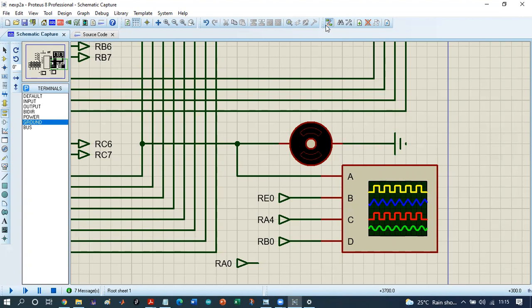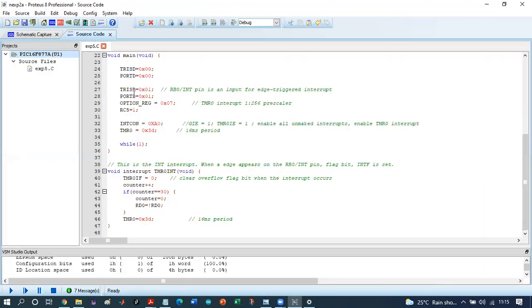So if you want the speed to be very fast, you set the PWM, the frequency of the signal, to be very high. Then if you want it to move very slowly, the frequency is going to be very low. For this particular code, like I said, the period is 3 seconds. So that's very slow.